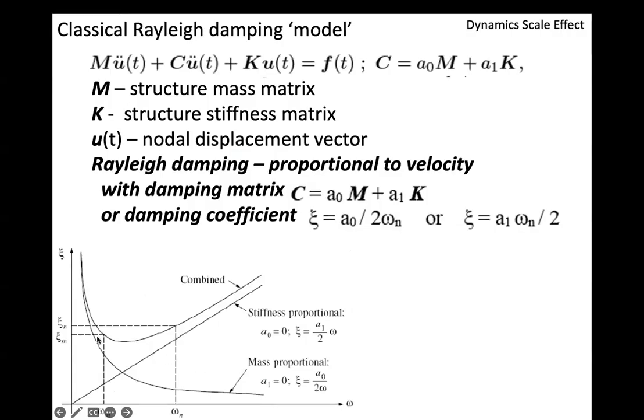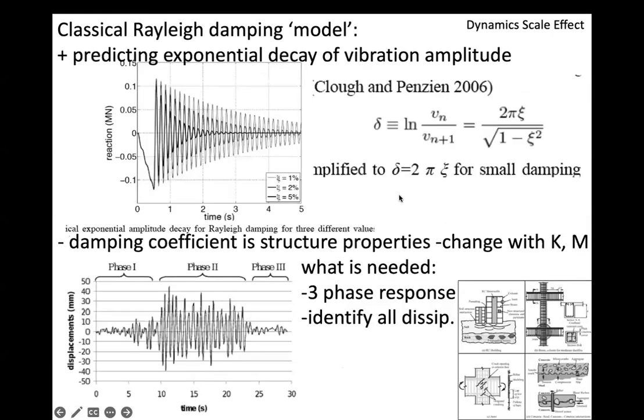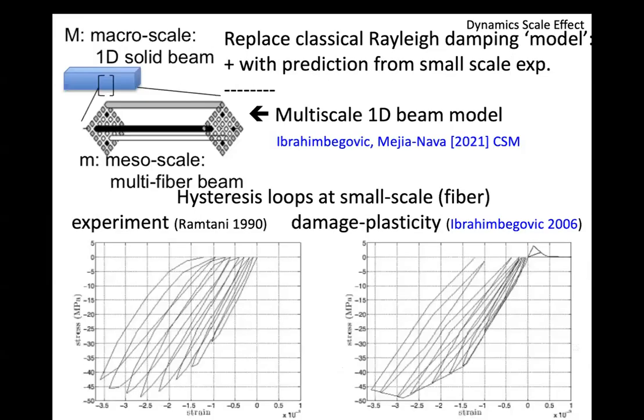And then typically you choose your damping ratio for a certain interval of frequencies. And even at those values, you have the damping you want, but not necessarily in between, or certainly not outside. So you can never really reproduce what you really need in terms of shaking, unless you go for this more refined modeling. And what is really good, you get this exponential decay. So if you want to get a refined modeling with plasticity, you don't have it; this is the kind of thing we discuss. You have all these types of results.